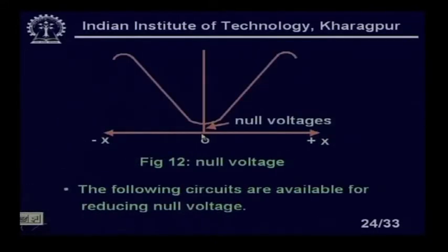You see, this is a null voltage. It is supposed to be zero, but it is not. Here you see the null voltage, the non-zero voltage I am getting at the geometric null position, right, because making two identical secondaries is almost impossible. So, some non-zero voltage will remain.